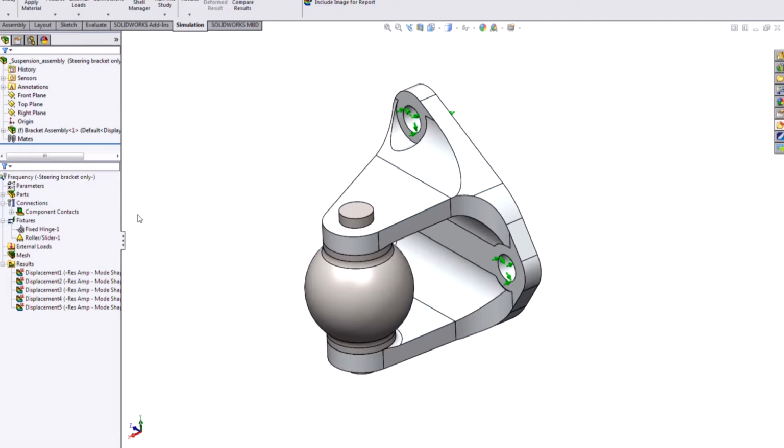If we're looking at the natural frequencies of the structure, we're running a frequency analysis. It's also called a modal analysis. Basically what that's doing is looking at the materials the object's made of, looking at where it's restrained, and identifying the vibratory frequencies that will cause resonance.